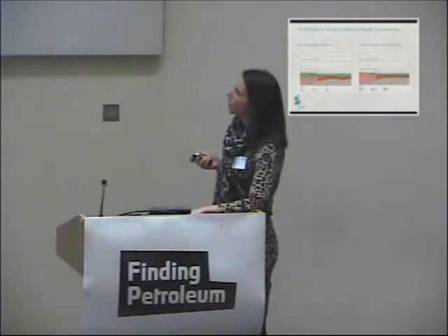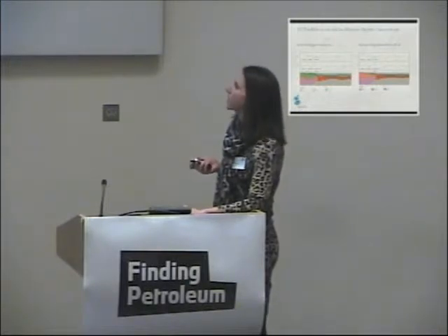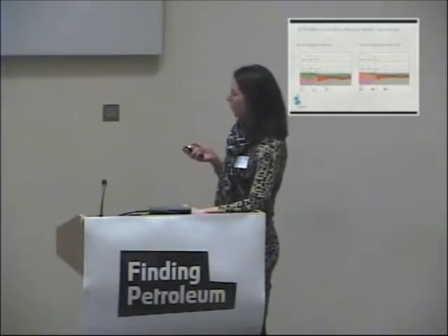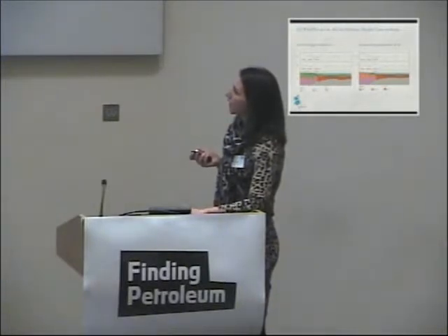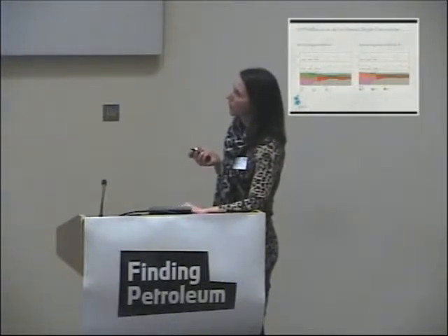Another application for our 2D profiles is using them as an aid to seismic depth conversion. So we had an example from the equatorial Atlantic where we had a regional seismic line that we were trying to model. It had very extensive depth to basement in the region of about 17 kilometres, and we wanted to double check that interpretation against our gravity and magnetic data.